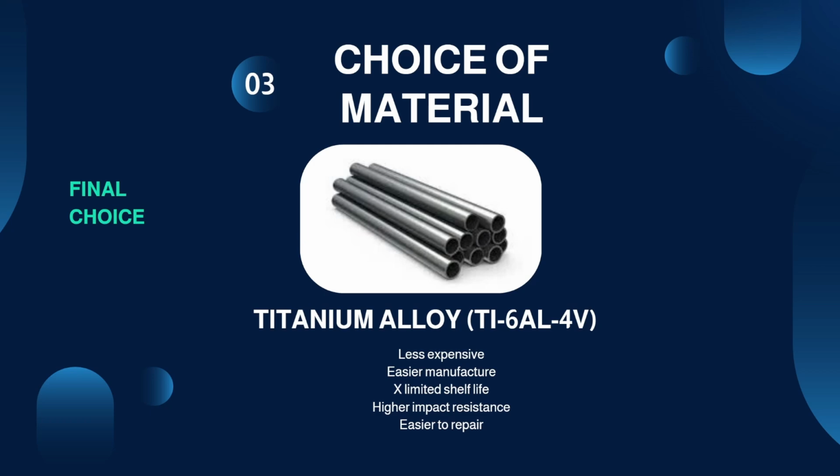CFRP also has another disadvantage, like limited shelf life, as the epoxy matrix will degrade and have reduced lifespan when exposed to sunlight, which is the condition for our usage. It has lower impact resistance compared to titanium alloy, which makes it bad for wheelchairs. It is also hard to repair, requiring specialized equipment, and is also a costly process.